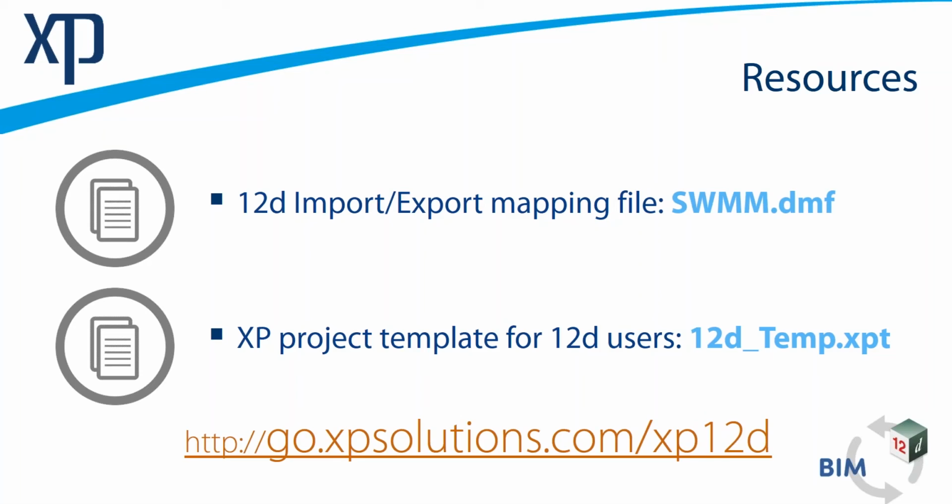That DMF file would sit inside your working folder. And that DMF is particularly set up for the Laurenson method. If you were using some other hydrology method, it could be altered, and I think we will plan for some future ones so that they could be used for EPA hydrology, SCS hydrology, whichever the case. And yes, those definitely sit inside the working folder.